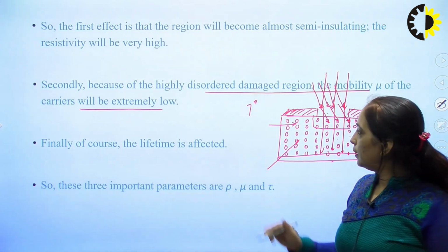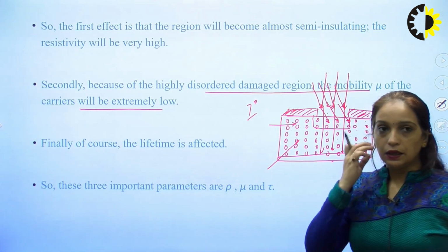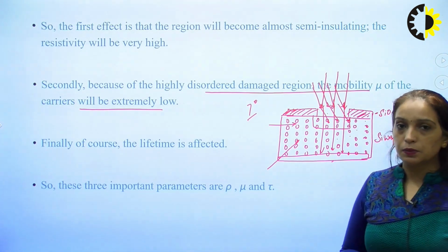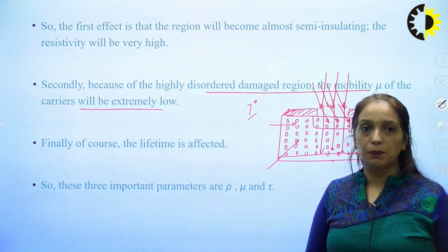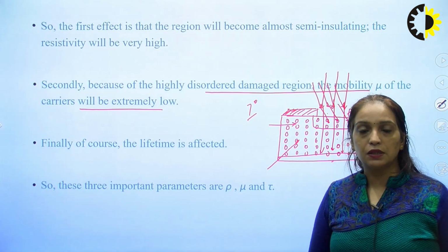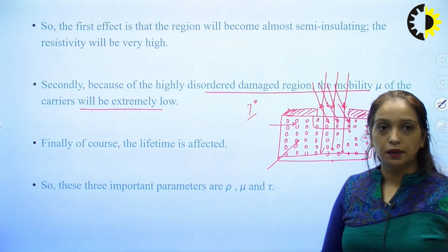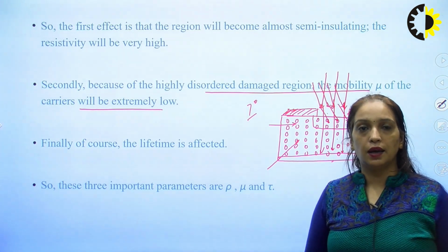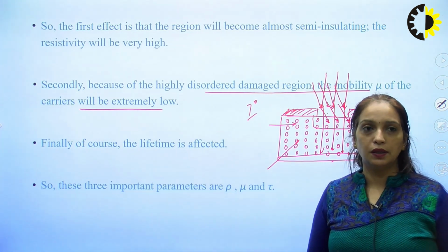By slightly misaligning the beam, the beam actually sees the substrate as amorphous. The crystalline surface is misguided to the beam, so that it behaves as an amorphous structure, and your beam will be stopped in the targeted region. This way your annealing is done, and the damage will be overcome, so that we can use the device for the next processes.